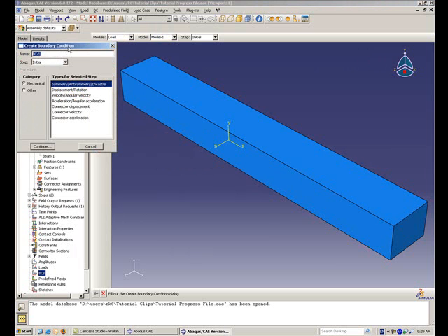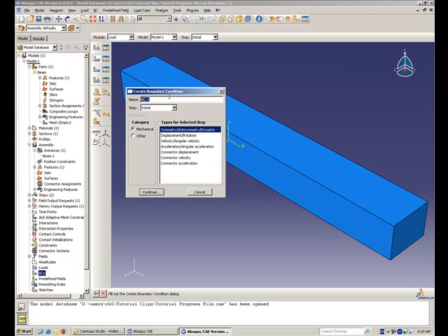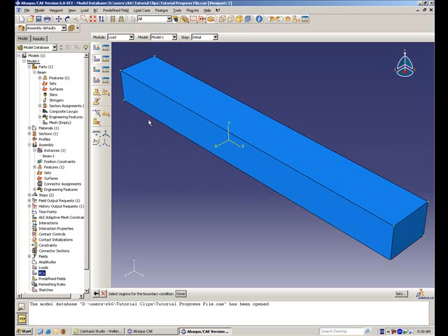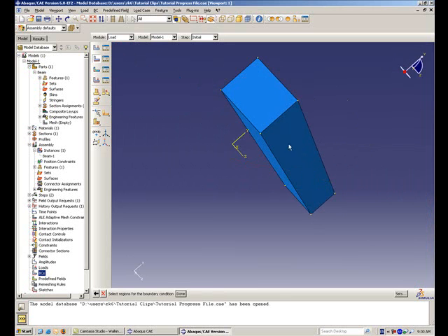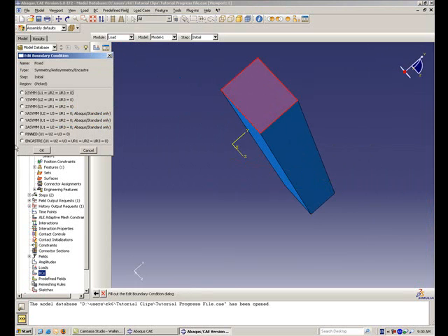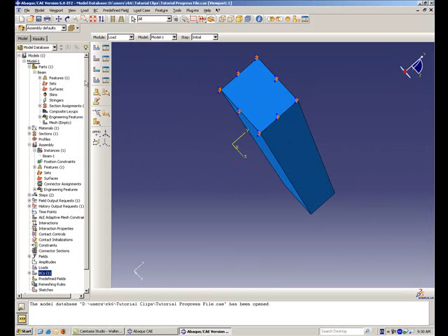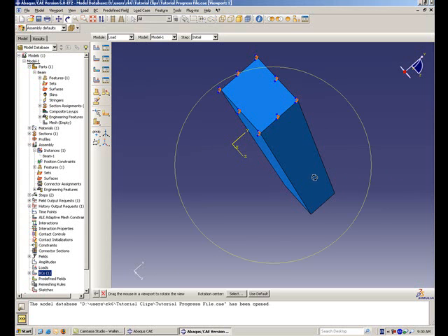The next step is to specify the boundary condition that is present in the initial step. To do this, double-click the BCs container in the model tree and name the new boundary condition Fixed. Select the initial step and accept the mechanical and symmetry settings. After clicking Continue, select the far left end of the beam. Hit Done in the prompt area and toggle on Encastre in the dialog box that appears. Because of this boundary condition, the left side of the beam will remain fixed during analysis.